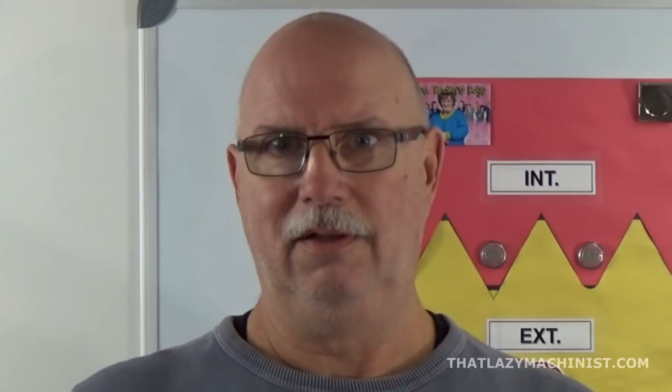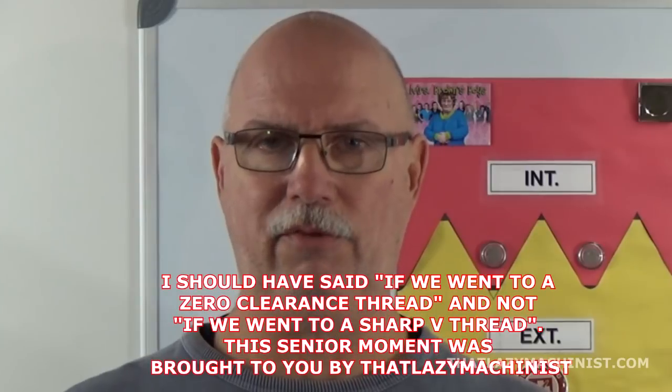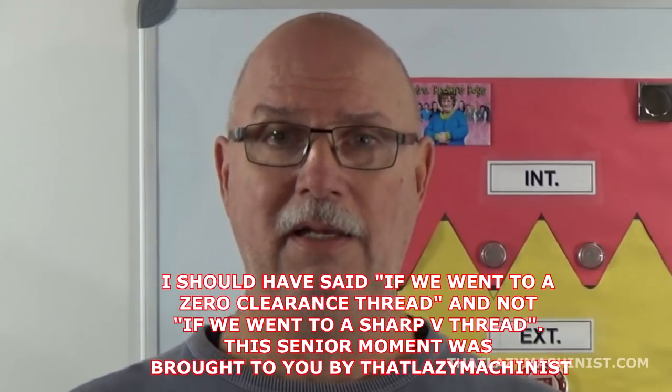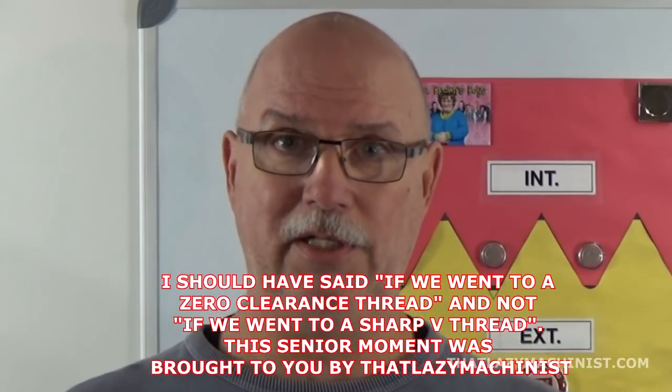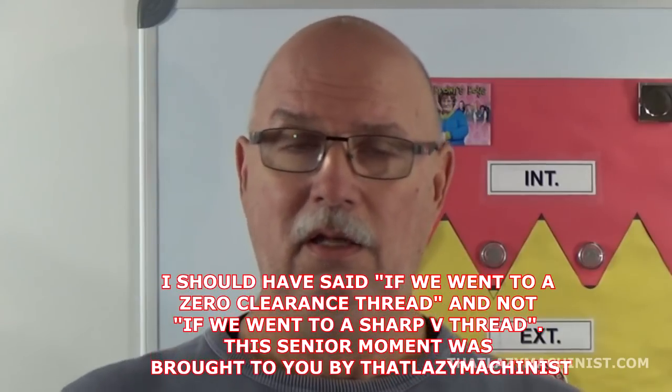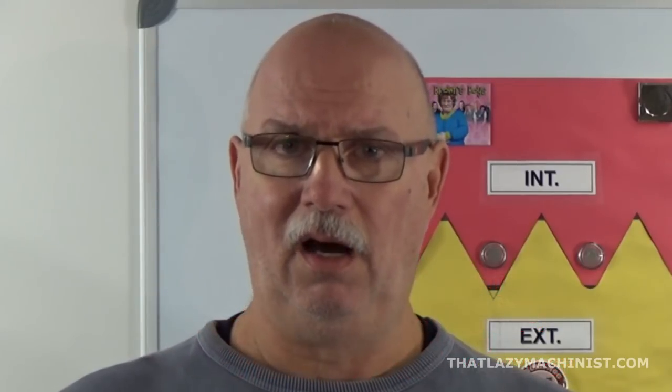Okay, a 3/8 16 is a thread that is quite popular. And its equivalent in metric is an M10 by 1.5. Now, 3/8 is the nominal dimension of the thread. It doesn't measure 3/8, but that would be its dimension if we went to a sharp V. So, 3/8 nominal.